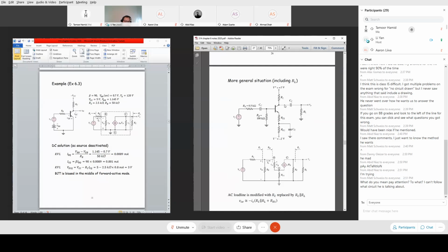How about the circuit where the previous output is right at the collector, but that just amplifies itself. You build the amplifier, well, you can say for fun, but that's not where you need it. You need to drive the amplifier result to your load resistance. Driving the load resistance, usually you carry the AC signal amplification. You don't need the full signal, so you need a capacitor to block the DC. So the true output ends up at the load resistance, using capacitor coupling. If you can see my cursor right at the collector, then if you define this as your output voltage and measure here with the oscilloscope, there is a full output voltage.